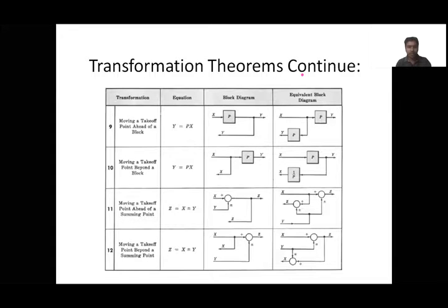And here, the takeoff point is moved from before the summing point to after the summing point. So after the summing point we get it like this. This is the way we can rearrange by shifting the takeoff point from before the summing point to after the summing point.